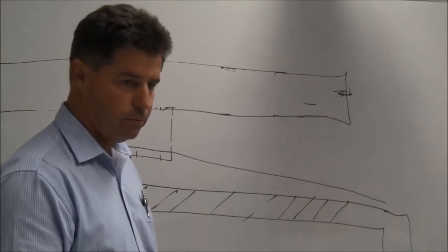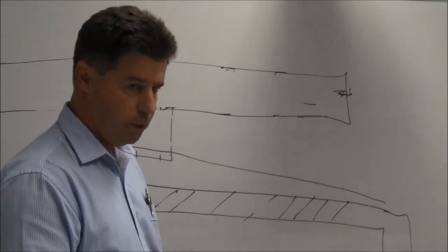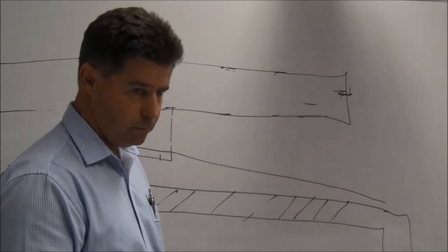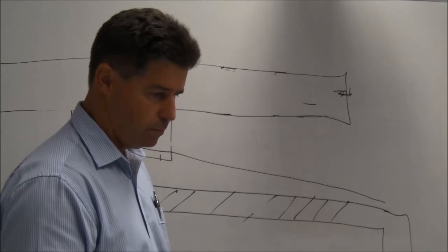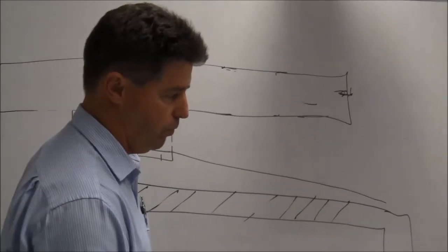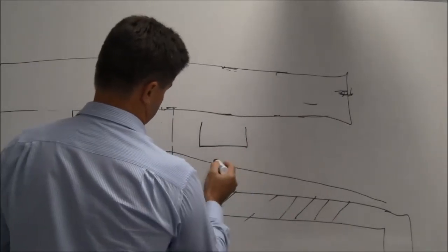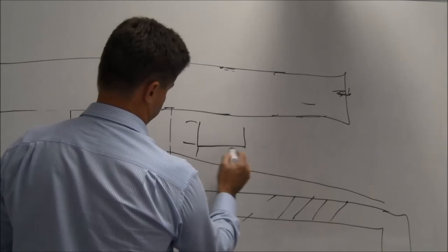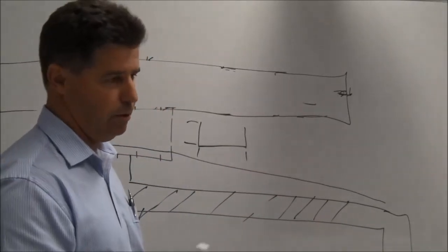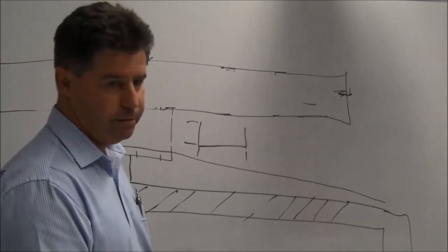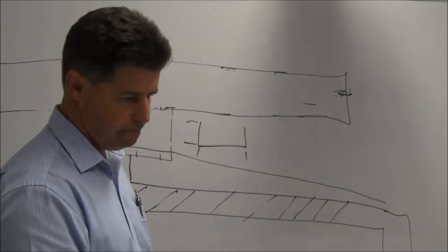I've got a question about the size of the eaves gutter. When we work it out as a cross-sectional area, how do you relate that to a square gutter and a half round? It's just the area. It's height times length. Okay, so whatever that is in millimetres. Yeah, so you might have to make one up. You might have to get something specially made. Not unusual. So our answer is just in square millimetres.